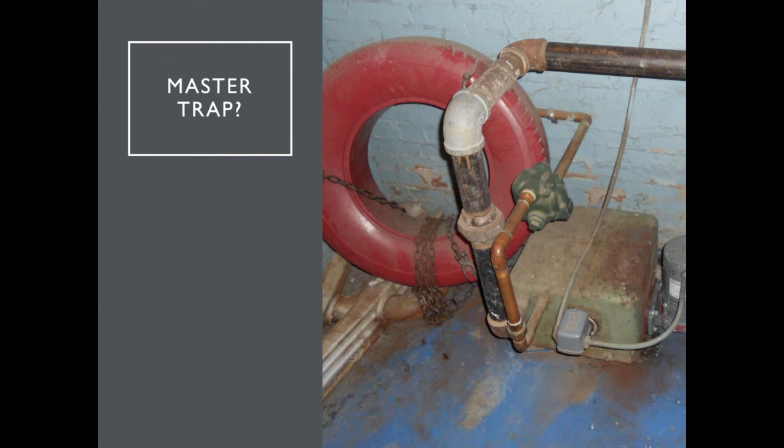Okay, and what's the most likely cause of short cycling of a two-pipe steam system? Either air in the system or a dirty flame signal or a dirty flame rod that's cycling on and off. But most likely it's air that I've found, the system is filled with air. And like Dan always says, two gases can't occupy the same space. So if I have air in there, the steam will not go into there. So you have to remove the air.